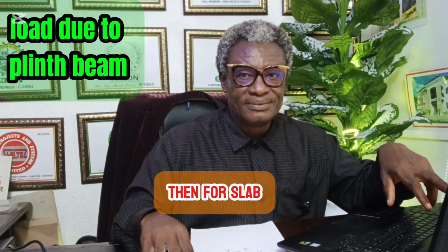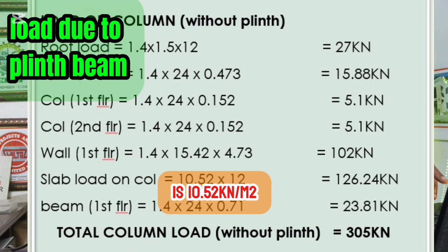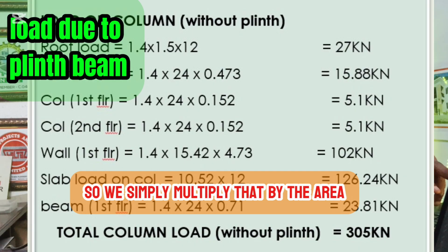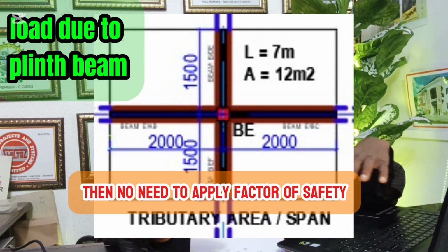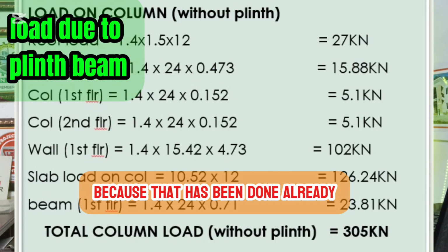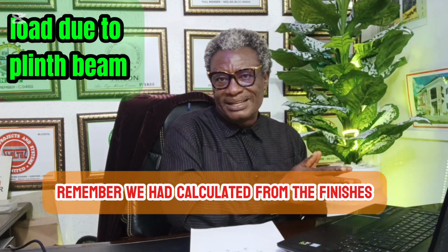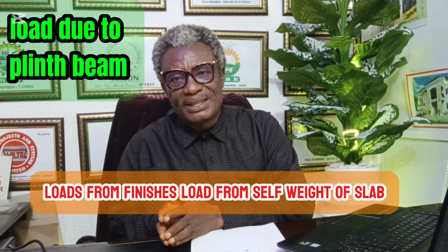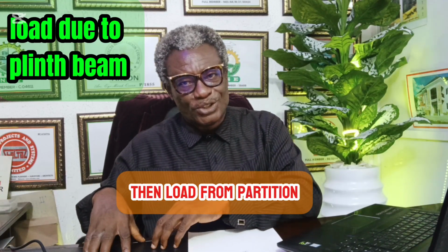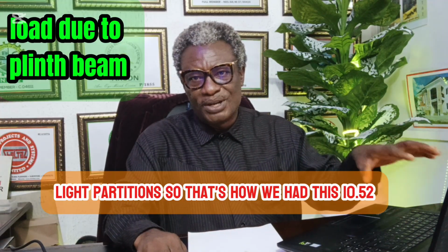Then for the slab, the ultimate design load for slab is 10.52 kilonewtons per meter squared. So we simply multiply that by the tributary area, which is 12. Then there is no need to apply a factor of safety because that has been done already. Remember, we had calculated the loads from finishes, load from self-weight of slab, then load from light partitions. So that's how we had 10.52.